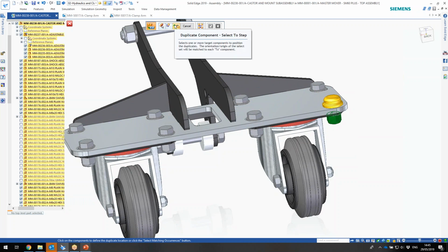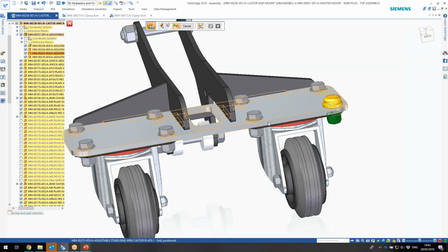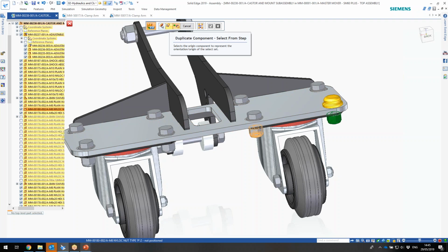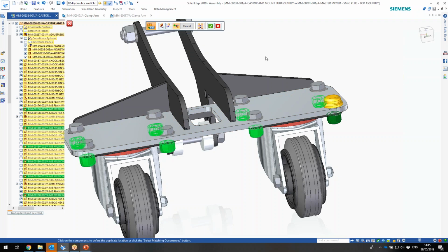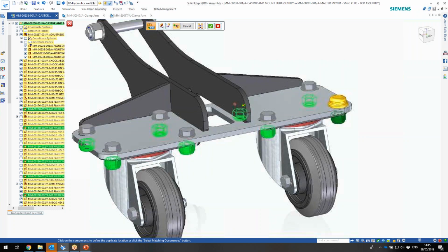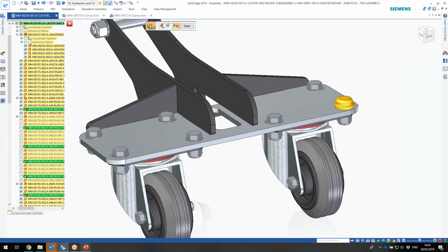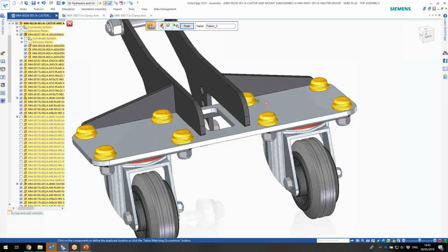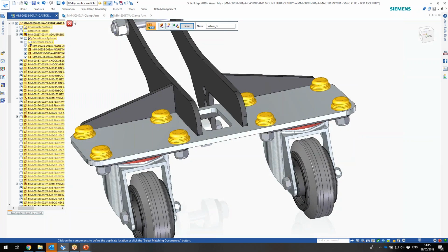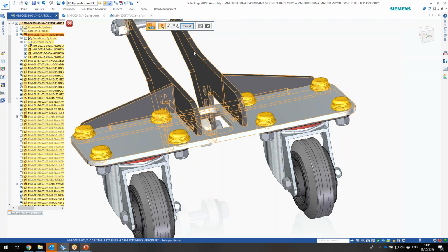And then right click. So it's found all of the other nuts in the model. And then we want to say OK. Now all of the bolts have covers. So I think that was a pretty cool feature, particularly useful when your pattern is not in a consistent arrangement. It could be a radial, it could be a range of bolts over a chassis or a panel. It finds all those bolts very quickly. Finish that,